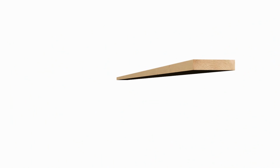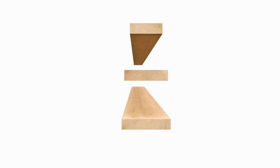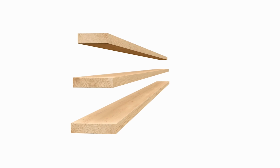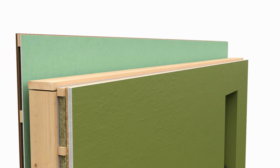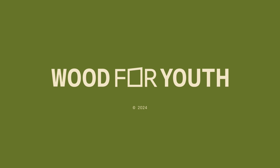The typical cross-sections of load-bearing timber frame for exterior walls are 45 to 145 millimeter, 45 to 195 millimeter, or 145 to 220 millimeter, but specific cross-sections are always specified by the designer.